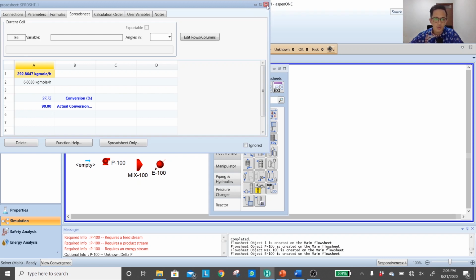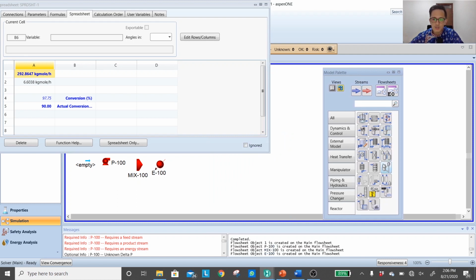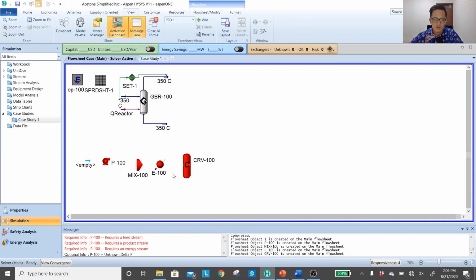And again, I will not directly model using PFR at this stage because it's just too much to do at this point of simulation. I want to finish the closed loop mass balance first, as usual, to prevent any unnecessary risk. Okay, so I will add my conversion reactor. I guess that would be enough for now. Let us mix all these things together.